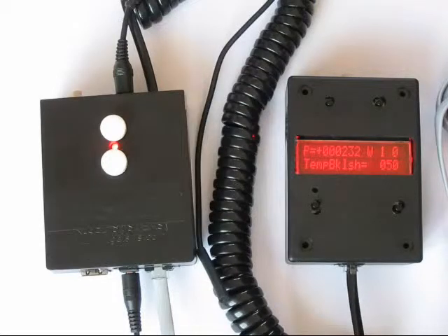Okay. And the next submenu item is backlash. If you have this hooked up to a stepper that's on a classic SCT and you've got mirror, focuser slop in there, and when you reverse direction you want to take up some backlash, this is how you account for that. This allows for anywhere from 1 step to 100 steps. Okay.